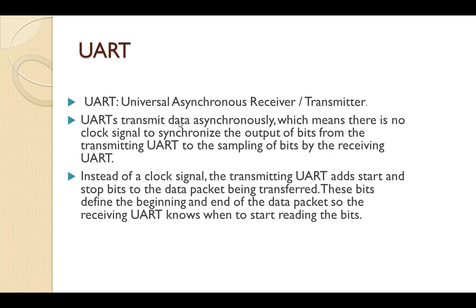In this UART, if you want to send data, we are not synchronizing with any clock signal. We need two bits, a start bit and a stop bit. When we get a start bit, it means the data transmission has started. Once we get the stop bit, it means the data has ended.